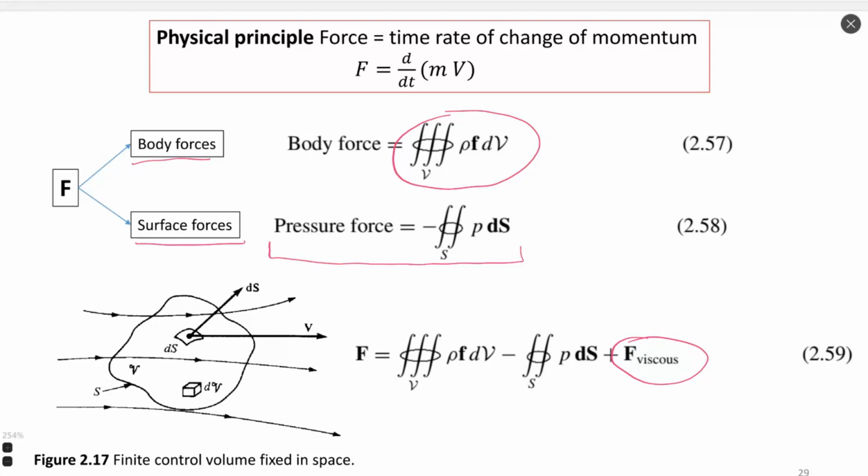And you know the reason for this. Usually it's because viscous forces cannot be solved analytically and can be solved experimentally, numerically. And this does not bring us any advantage in the analytical solution of aerodynamics. It only brings more complexity, but they are necessary. For example, you remember for a streamlined body, the flow of an airfoil, the drag is composed of viscous forces. So we need to know viscous forces to calculate drag. And this is done later.